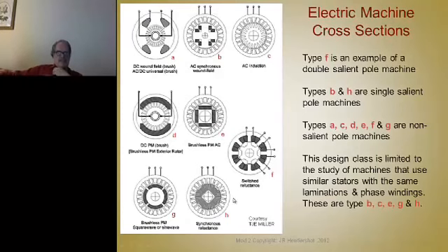And now here's an extreme example of a reluctance machine that has poles that look like a gear on the rotor and poles that look like a gear on the stator. If you look at this winding here, the flux is going to go through there like that. There's very little air gap in the circuit. It's all iron, very tiny clearance gap there. But in this set of poles, there's lots of air gap in the circuit. You've got this great big air gap in there. So the inductance here is very low, and the inductance there is very high. There again, we're in quadrature here.